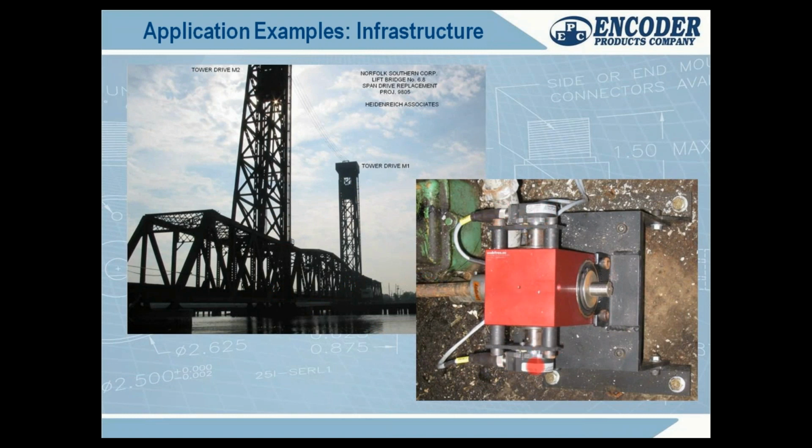This is becoming more and more common. In fact, I'm doing a lot of custom applications to fit redundant feedback into specific areas in equipment, and it's for safety. So they're running two discs and two reed heads redundantly on this shaft. Reason being is that they always need to equal each other. If one of these encoders ever deviates more than a couple pulses from the other encoder, the whole system will e-stop and go, all right, we have an encoder failure.